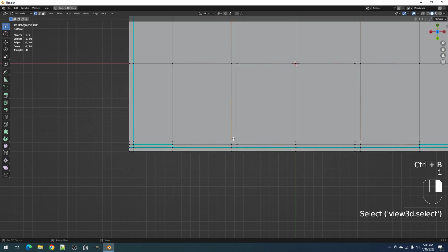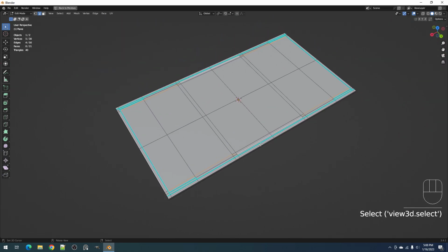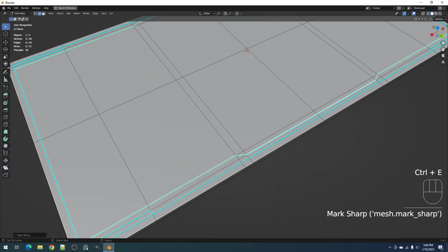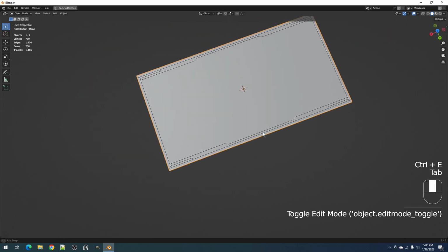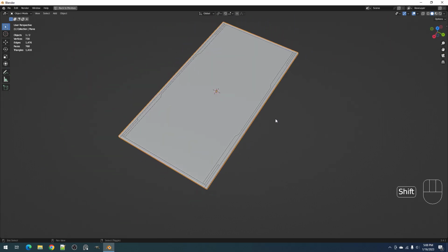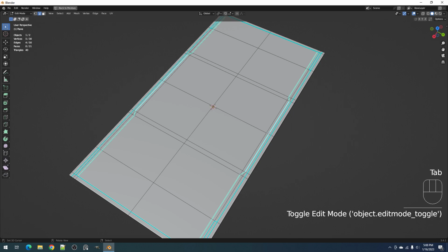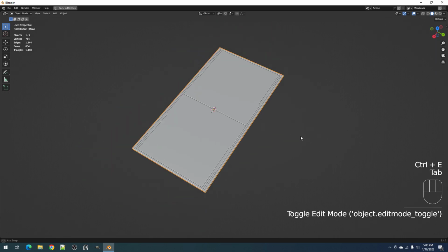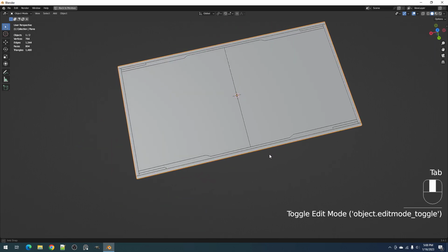and this will also work with stuff like character armor. You can create the armor out of planes and just add the solidify, the bevel and the edge split modifier, and you can just detail the armor assets that way, and just bake the panel cuts afterwards.